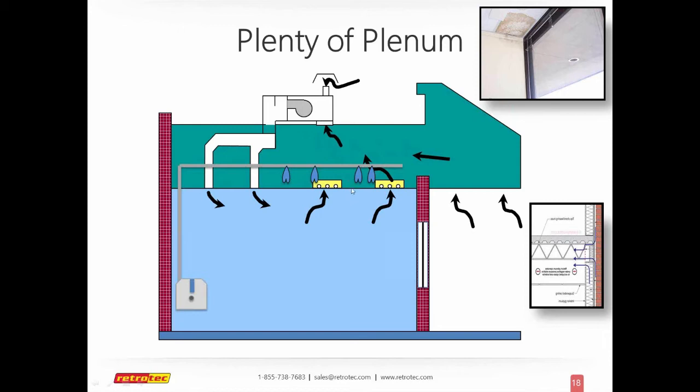And the challenge is, where is that actually connected to? A lot of times it's open to any part of the exterior walls, the neighbor's walls. Sometimes it even goes directly into the neighbor's unit. And most commonly it'll go to the out front with a walkway. So if I'm trying to figure out why I have stains on the ceiling, a lot of times it's because I'm actually bringing in temperature and moisture from the front walkway into the plenum area, and then I end up with condensation issues with ducts or water pipes that are there.